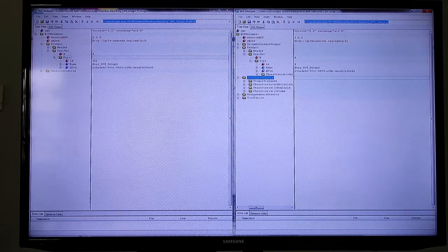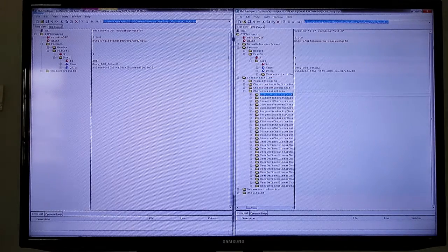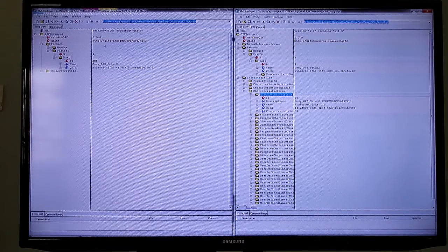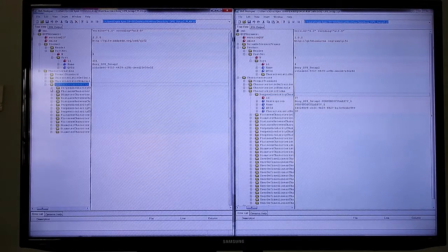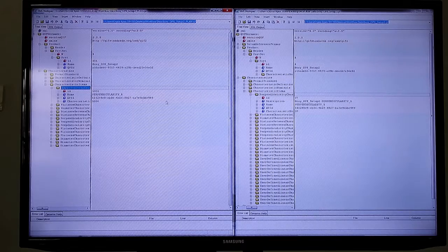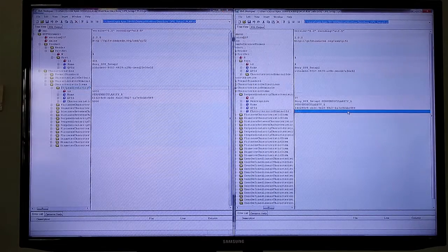If I go to my characteristic items, here with perpendicularity, there's one UID. And just to demonstrate, everything is tracked all throughout the process. All features have been properly labeled with the same UID. And now a QIF reader that is hopefully being developed pretty soon in this new standard would be able to present this and track this throughout the process.